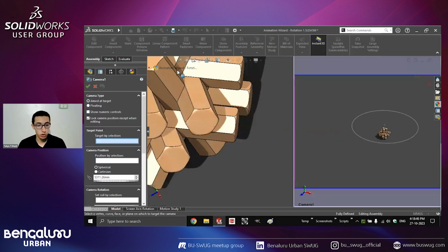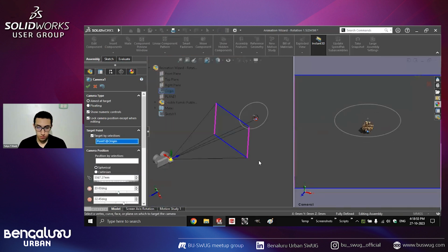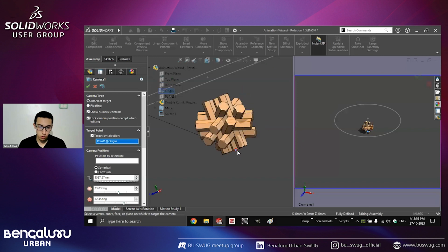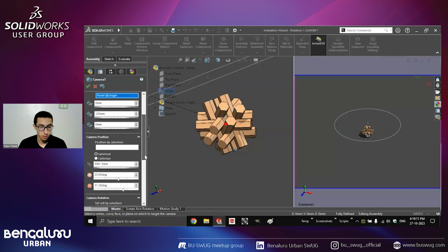And I'm just going to show the numeric controls. The target, I want, let's say, the origin. The origin is a bit low, so here's a nice tip. If you want something to be relative to that origin, I just turn this off. The y-axis, let's say 125 millimeters. So now I'm off in the y-axis by that, so I can mix and match between my choices.